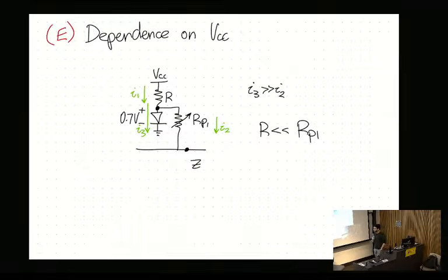Now, some other solutions I think I saw some students put last year was putting in a linear dropout regulator. Now that's sometimes good with power supply rejection ratio. So that's good for helping with minimizing the ripple on the power supply. But fundamentally, we still have the same problem of VCC being connected directly to the node. So it does loosely fix the problem, but it's not the main problem at hand. So that solution might get you partial marks.